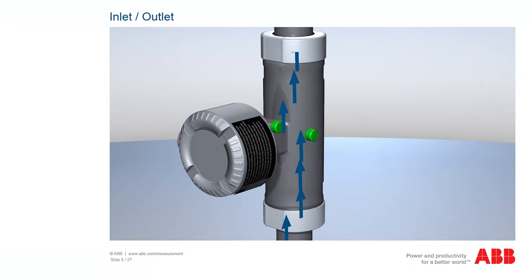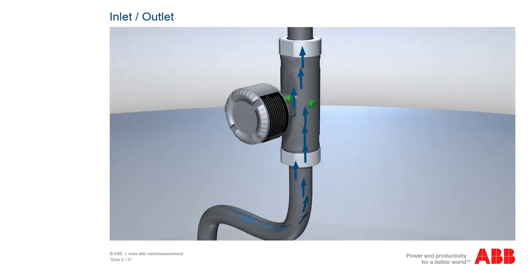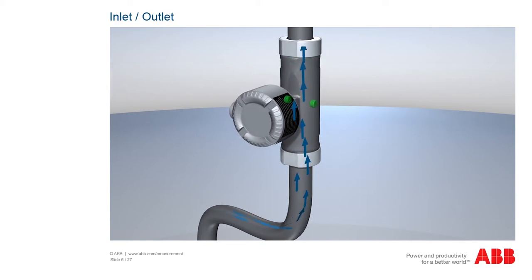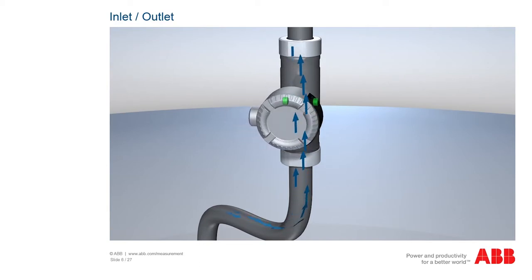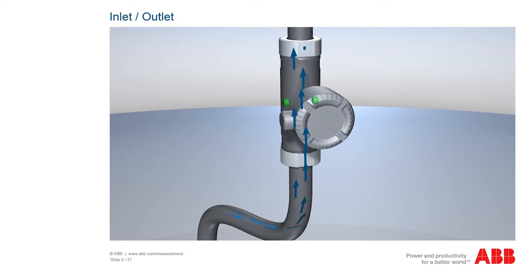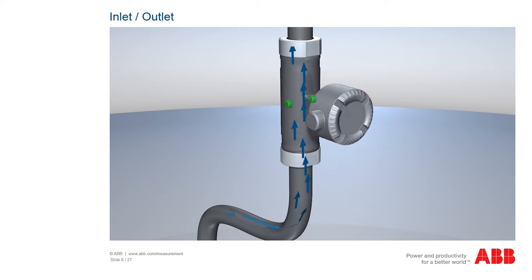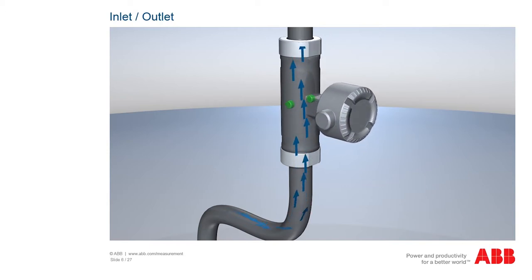The mounting position of the flow meter is also important. Because of the unfavorable flow profile caused by the angle, the two measuring electrodes record different values. As the flow meter has been correctly attached, both electrodes are positioned in the central area, which means that the measuring errors can be largely compensated for even in unfavorable system installations.